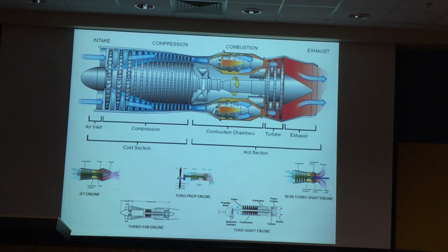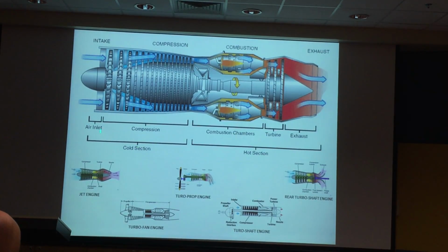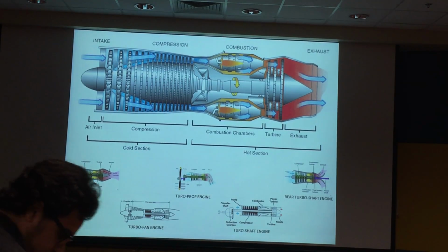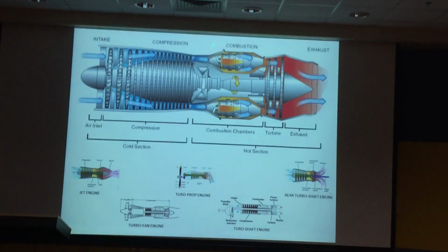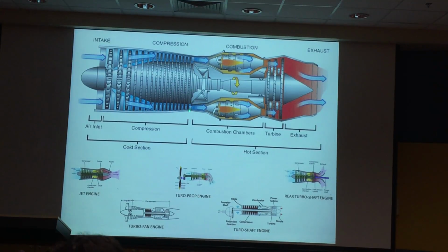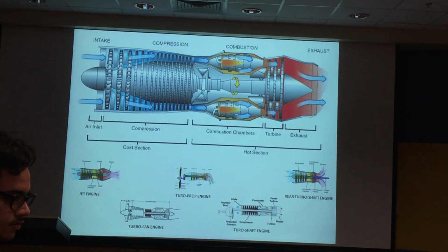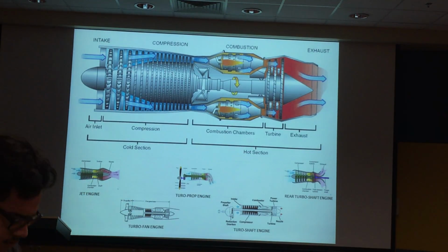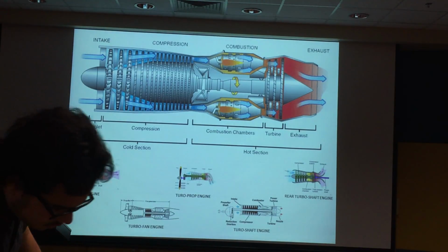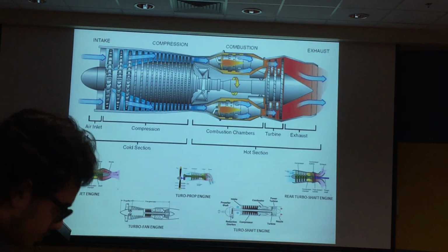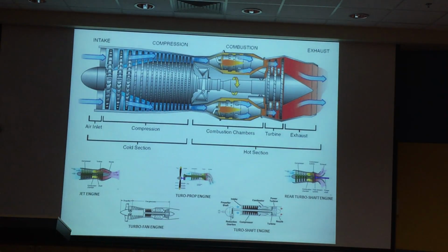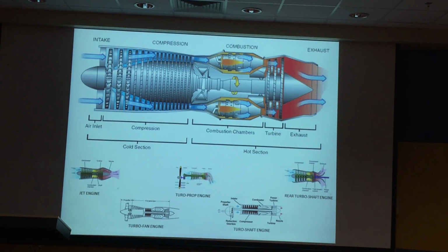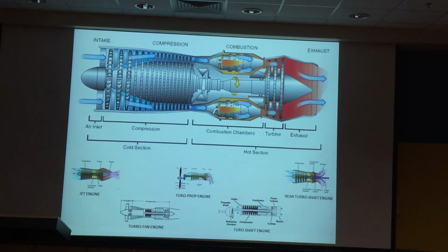Okay, you also need to understand the basics of your engine construction. Where is the intake, followed by the compressor. Then the next one is the diffuser. So what is the purpose of the diffuser? The diffuser is just an empty space, a diverted empty space, to enlarge the volume. To give you what? To increase the pressure. There's some drop in velocity.